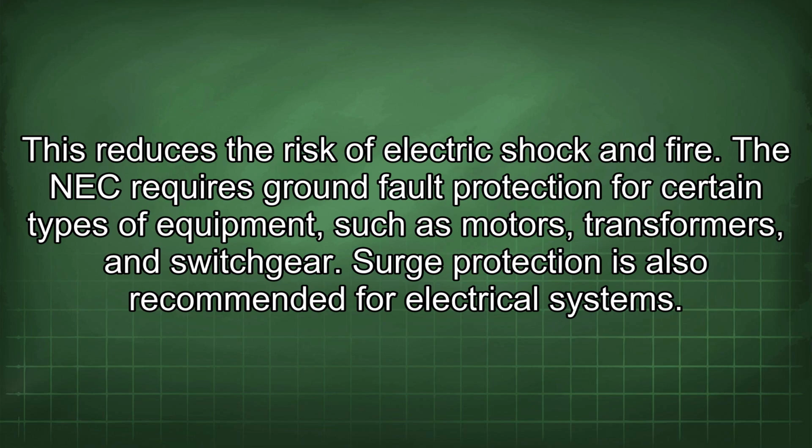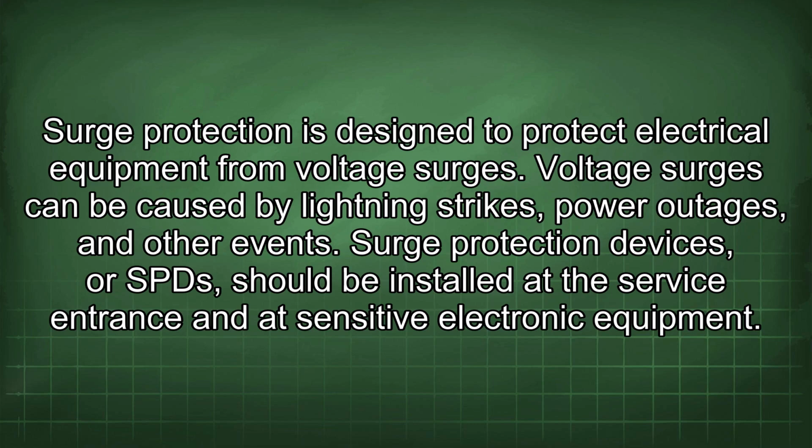Surge protection is also recommended for electrical systems. Surge protection is designed to protect electrical equipment from voltage surges. Voltage surges can be caused by lightning strikes, power outages, and other events. Surge protection devices, or SPDs, should be installed at the service entrance and at sensitive electronic equipment.